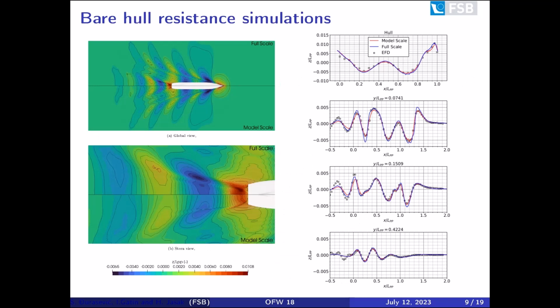Accurate capturing of the free surface is also important to determine the wave-making resistance force, which is necessary for the self-propulsion computations using a double body model approach. Overall good agreement with experimental data is obtained if the wave elevation is observed.